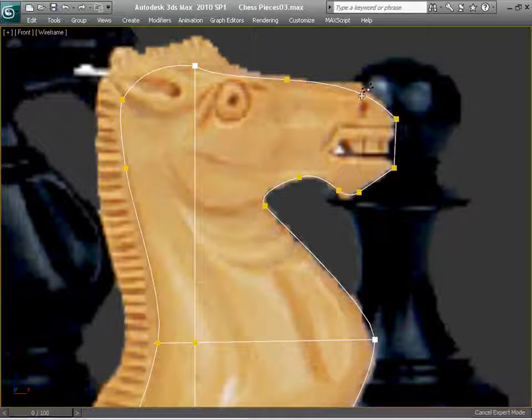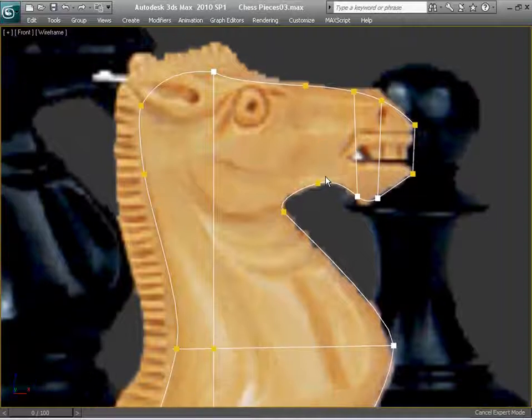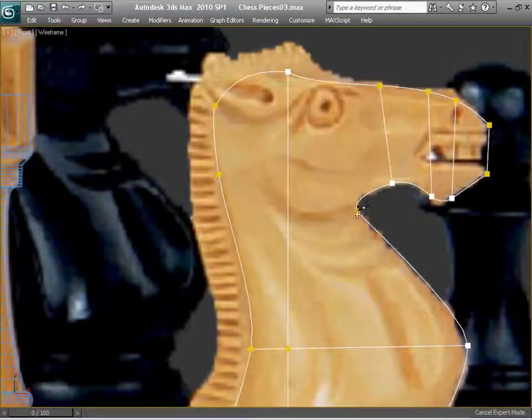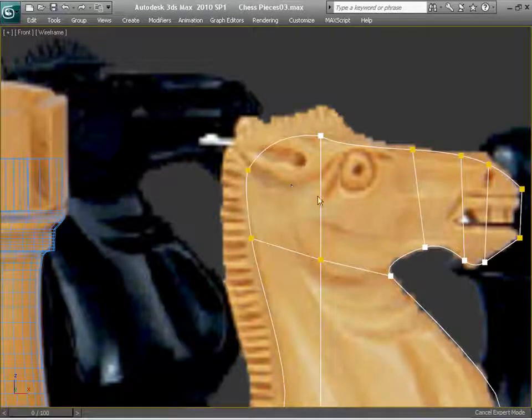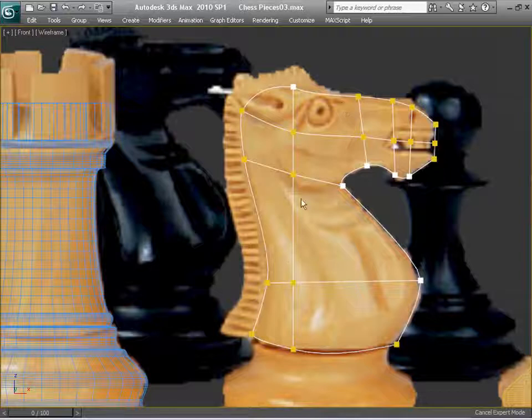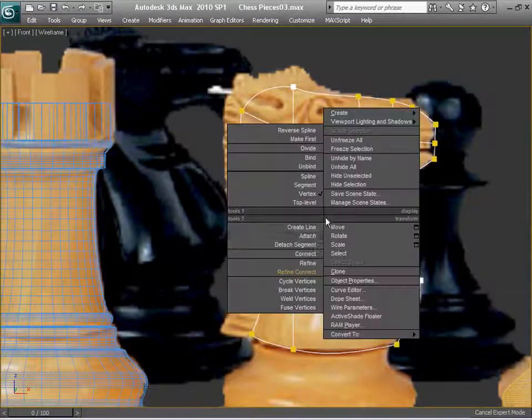And I'm going to be talking about why we are doing this and some things that we have to take into consideration when we are doing this. At the end, when I finish creating the lines that I need, I'm going to be applying the surface modifier, and that will allow me to have, let's say, a skin on this particular spline. That is the one that we're going to be using for creating the three-dimensional object.